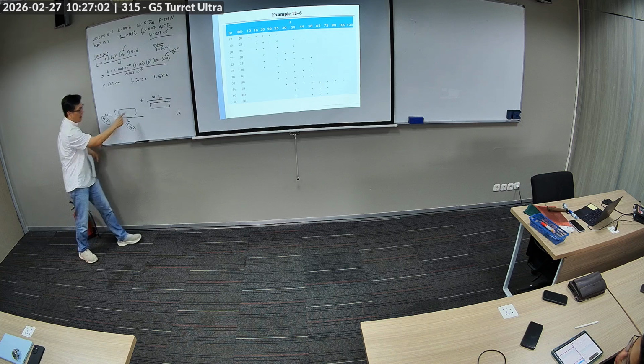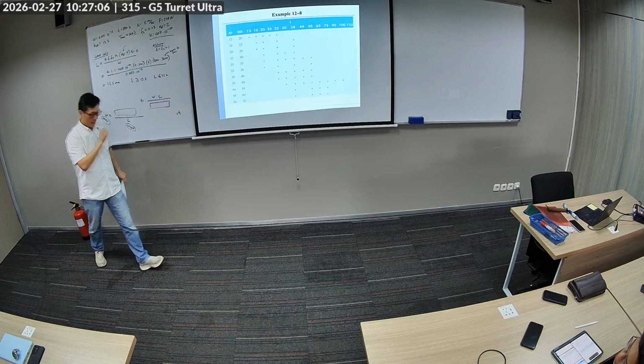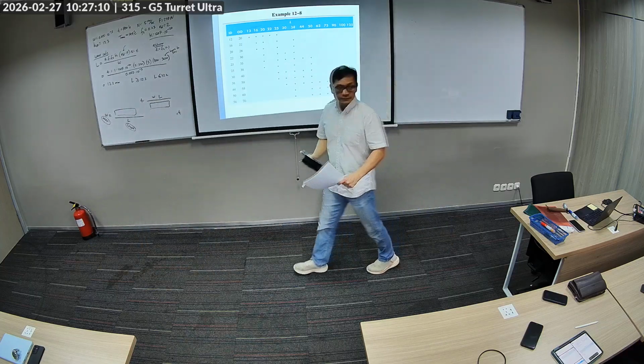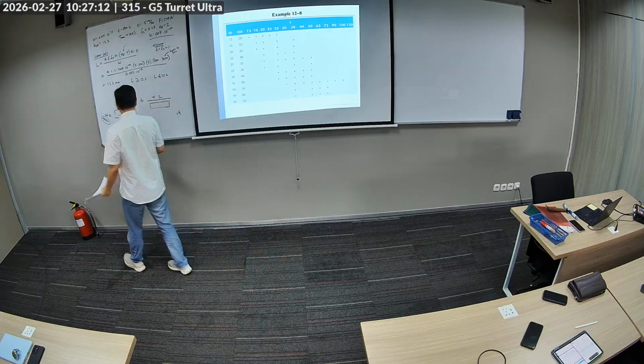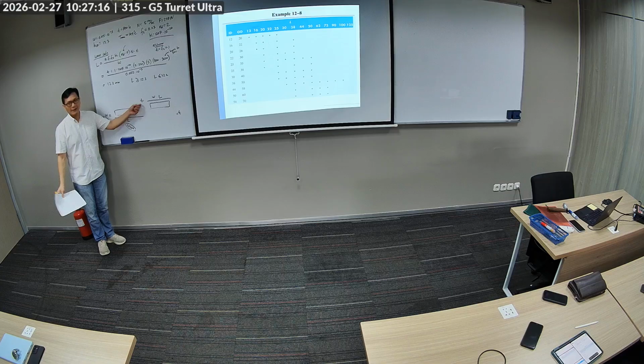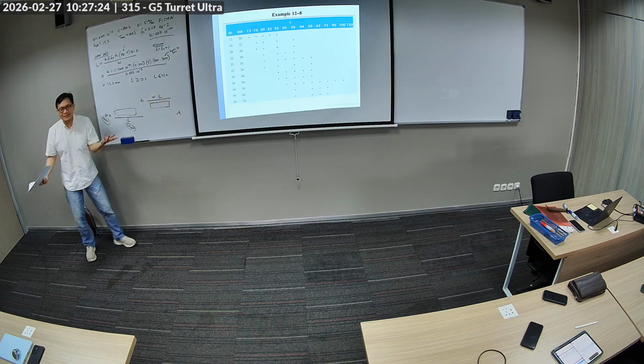So how is time or lifetime related to L? Meaning, do I want high lifetime or low? High lifetime. Which means high L, long bushing, bigger area, which kind of makes sense, right?